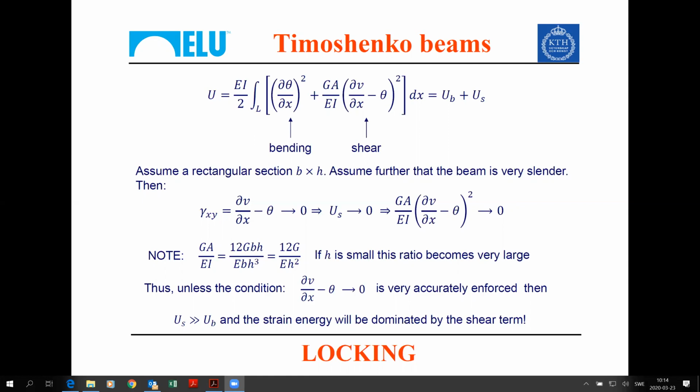If you see that starting at some L over H ratio, you start to have less displacement than in previous cases, then you have a locking problem.